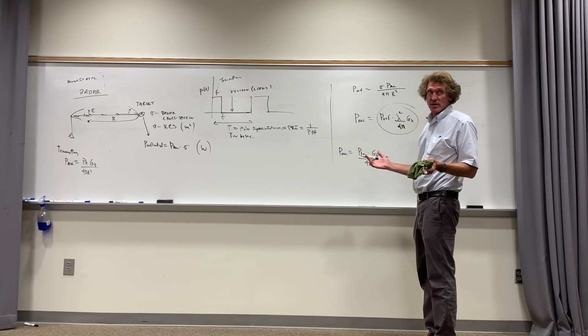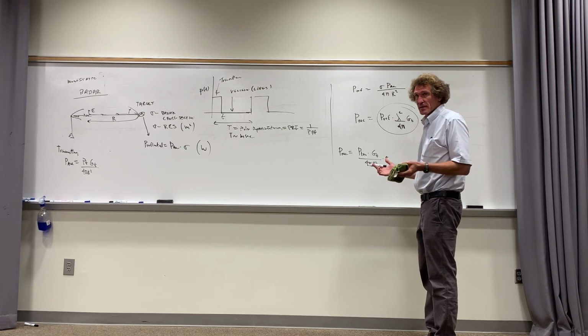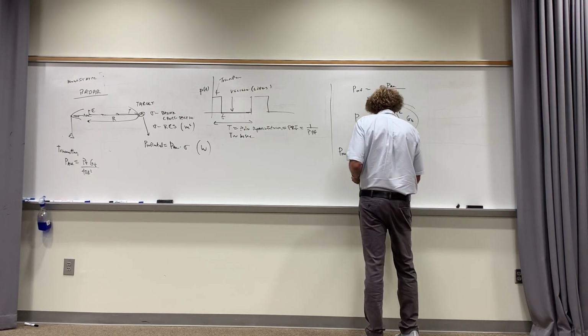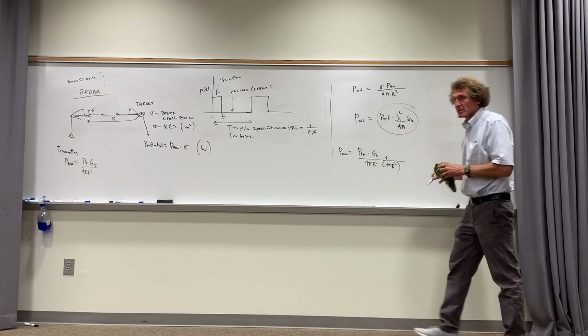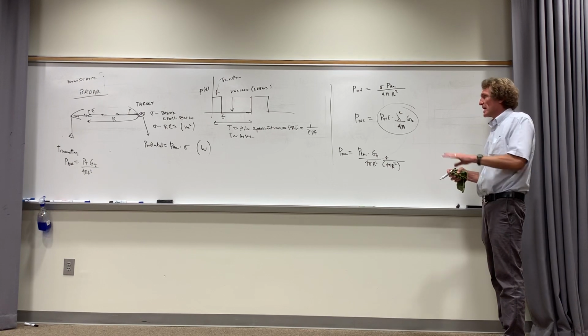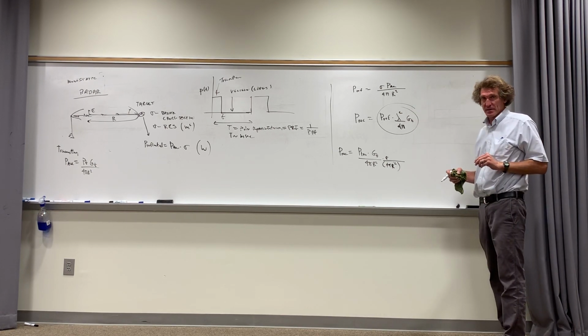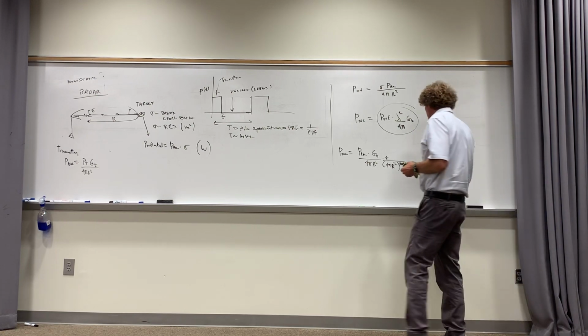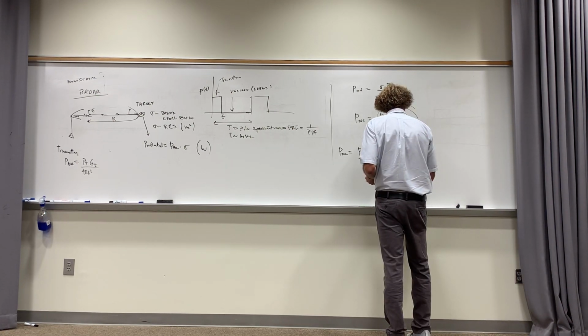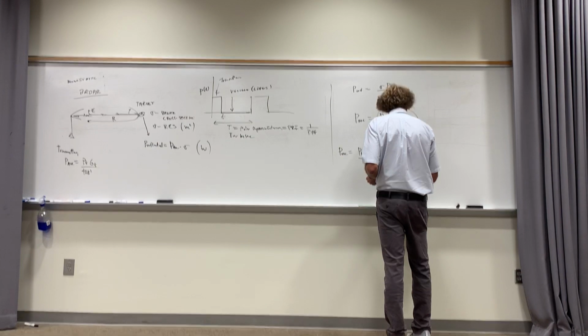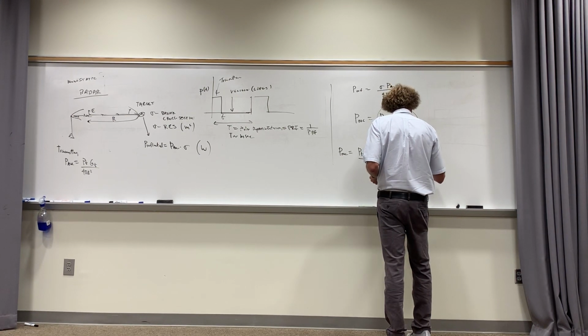Sigma is the RCS. Agree, class? Now I take that and I have to divide that again by 4 pi r squared, because now that's the amount of power that's actually incident on the antenna that we transmitted from. Agree? Then I have to take that and multiply it by lambda squared over 4 pi times the gain of the transmitter again. Correct, class?